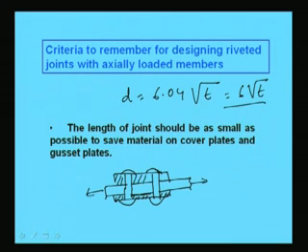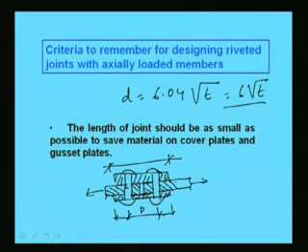Now, you see this is called the pitch and this is the edge distance. So, this pitch and edge should be as small as possible, so that the length of the extra cover plate, whatever we are introducing for joining the two plates, is as small as possible.